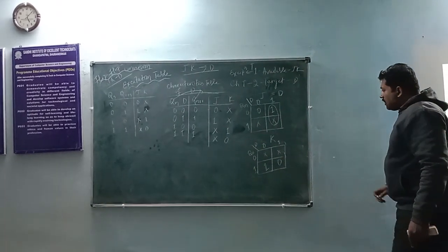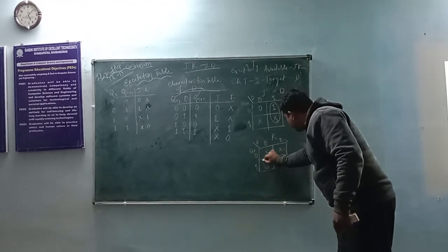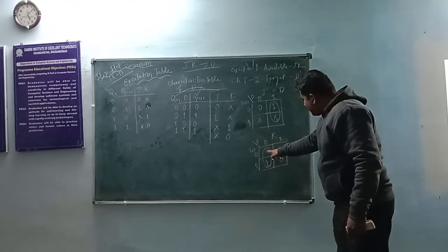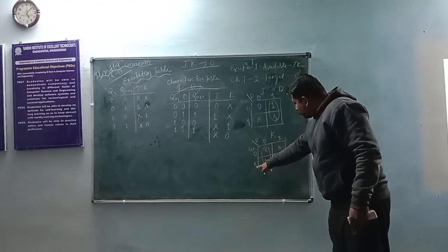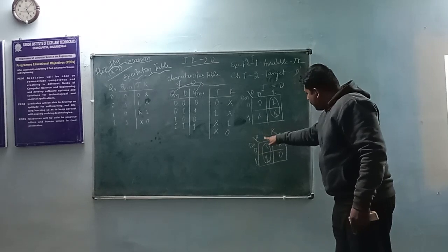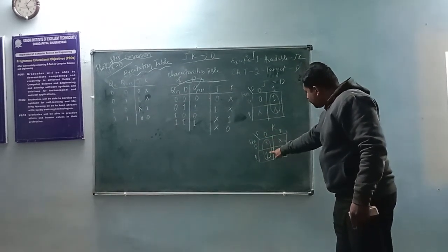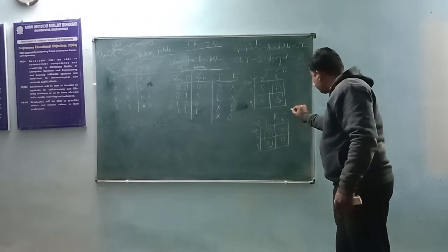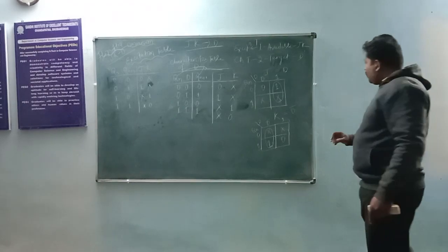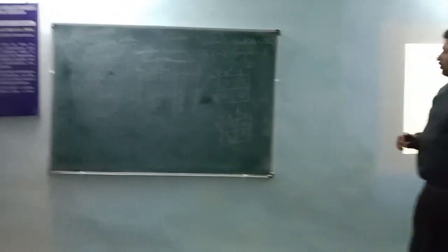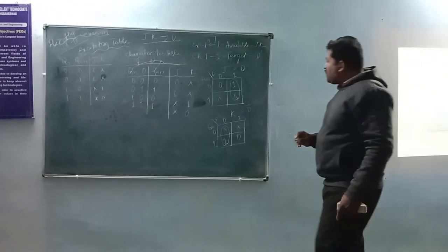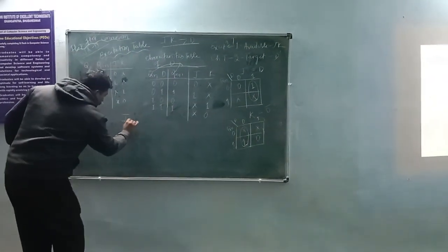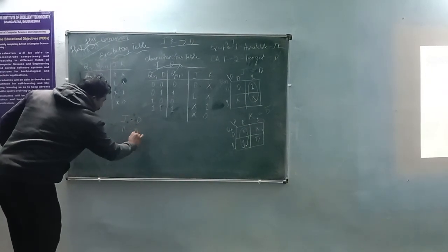Again in this K map, a single loop is possible by taking this 1 and don't care. Here you can see that Qn is changing its value from 0 to 1, so you cannot take it, as the D value is constant for both outputs. Because this one is 0, we can write K is equal to D bar. So we have designed the equations J equal to D and K equal to D bar.